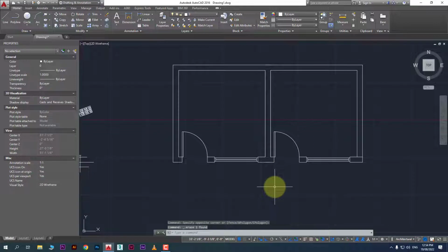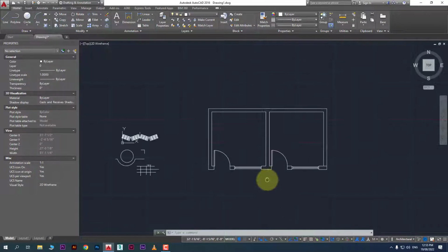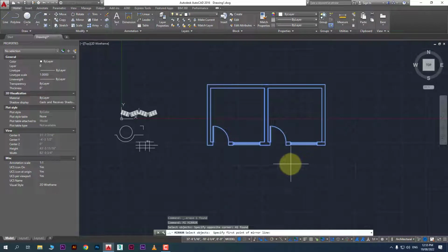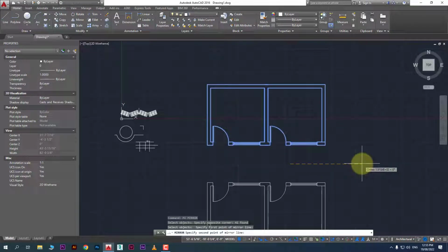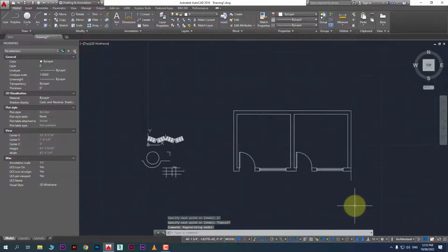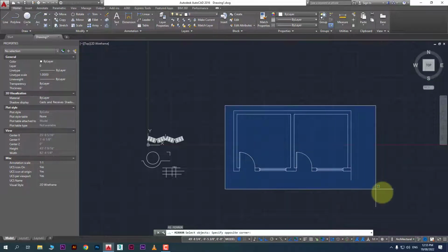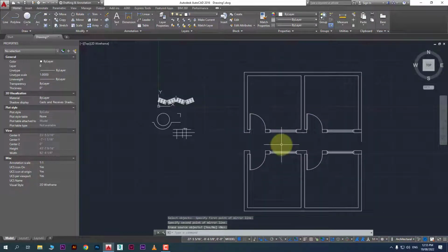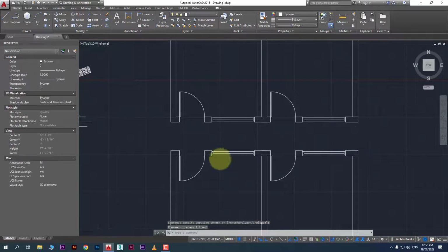So these two rooms with the same door direction. All right, now you want to mirror two rooms in front of the same. Then what you will do, mirror, mi mirror. Okay, and select this one and just mirror line like this. If you want to specify distance, so half distance you will specify here, like we have 2 feet. Okay, like this. So now you have to select mi mirror, select both room and this point. Now like this. Now you have 4 feet corridor between this.